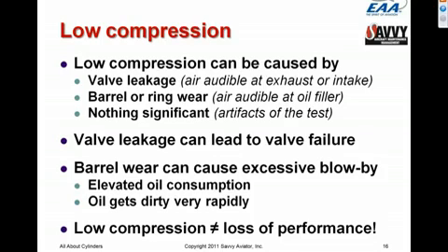Now they didn't go any further than 40/80 all around, because by the time the engine was at 40/80, there was so much blow-by and so much pressurization in the crankcase that the oil was getting totally filthy, and massive quantities of it were blowing out the breather, and they just weren't able to run the engine very long without running out of oil. But they never did get any measurable loss of horsepower. So the notion that cylinders get tired and engines get tired over time is just not correct.